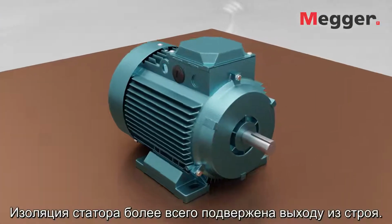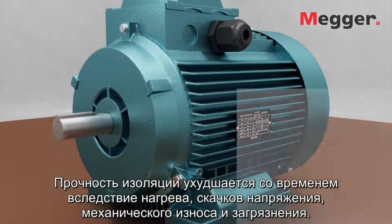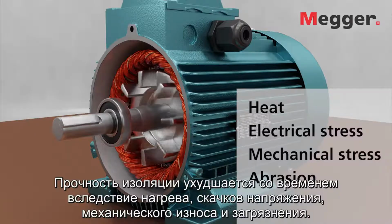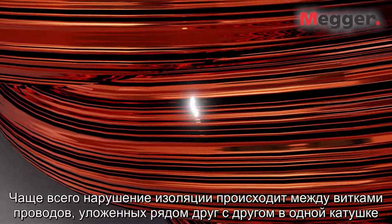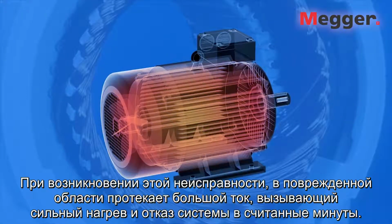The stator insulation is most prone to failure. Insulation strength degrades over time due to heat, electrical stress, mechanical stress, abrasion, and contamination. The most common insulation failure is between turns of wire that are next to each other in the same coil. This is called a turn-to-turn fault. When this fault occurs, the motor will draw a lot of current, quickly overheat, and can melt down in minutes.